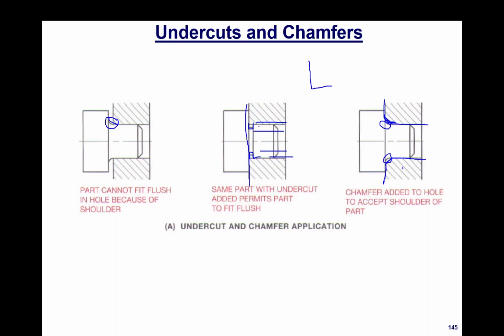And you might argue and say, well, a chamfered hole appears to be like a countersink, and yes, that's true. It is similar geometry to a countersink because it's a conical shape in all essence, but its purpose isn't to align a fastener or anything. Its purpose is to break the edge and provide some clearance for a mating component. So chamfering also allows us, if you look at the end of this shaft here, the end of the shaft is also chamfered here, this angle here.